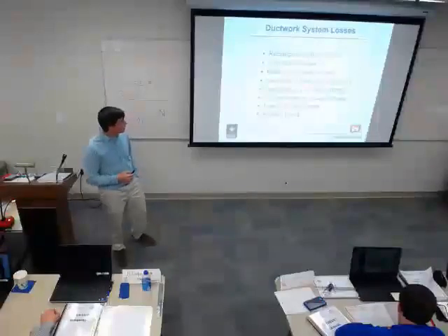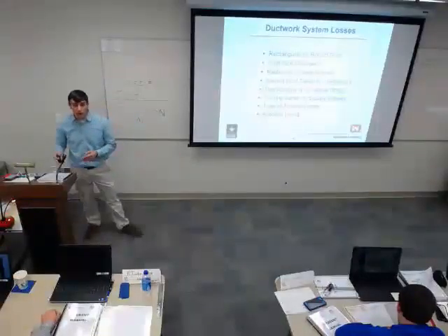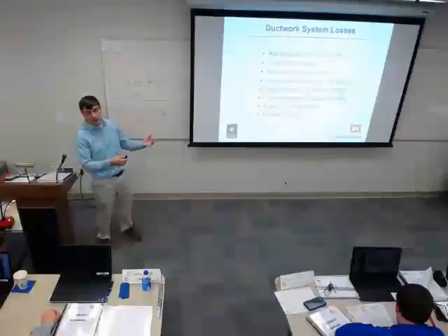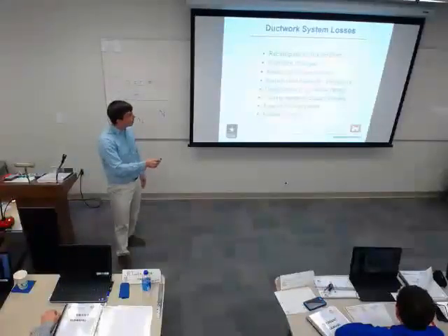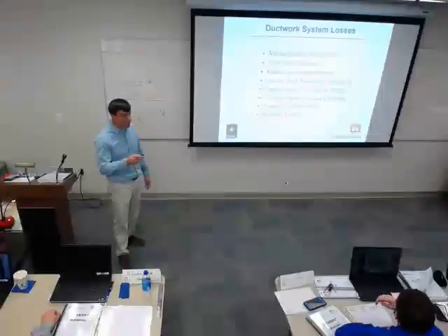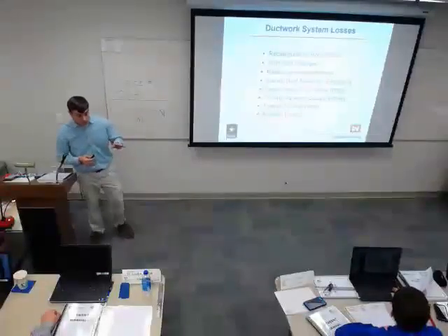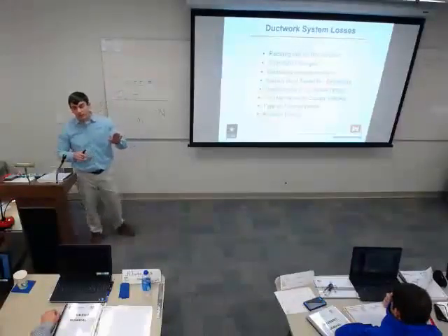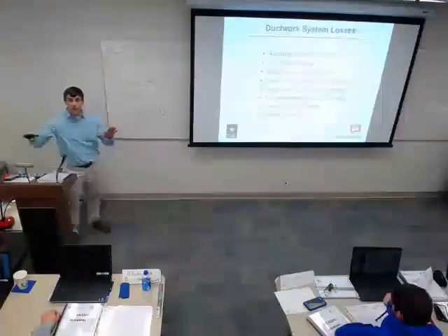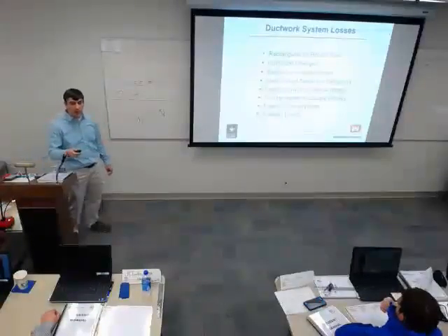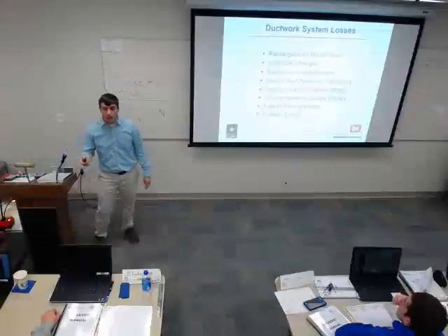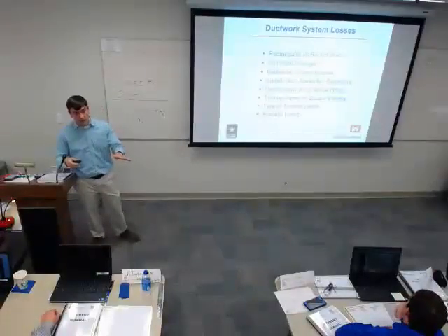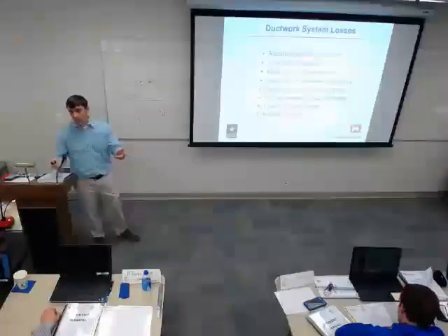Okay, so kind of bringing this back into the QA realm, what can we look at as construction progresses that might impact all those readings that we've been talking about? The type of ductwork. He showed you a slide earlier that showed the pressure loss for a 144 square inch round duct is different than the pressure loss for a 144 square inch rectangular duct. So duct size does matter. A contractor says, hey, we don't like round duct, we'd rather do square duct, we'll give you the same area of duct. Is that okay? No, it's not okay.